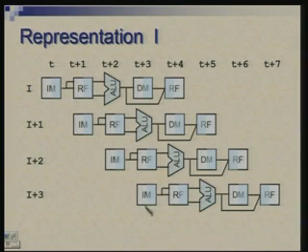So, you have instruction after instruction entering the pipeline, and you can show multiple instructions by showing them staggered in terms of their stages like this. Now if you want to look at a snapshot at a particular time, for example, let us say time T plus 3, you have instruction I in DM stage, instruction I plus 1 in ALU stage, instruction I plus 2 at RF stage, and instruction I plus 3 in IM stage. So, the second representation which I mentioned will try to capture this.